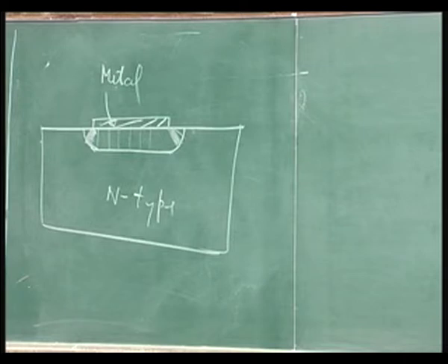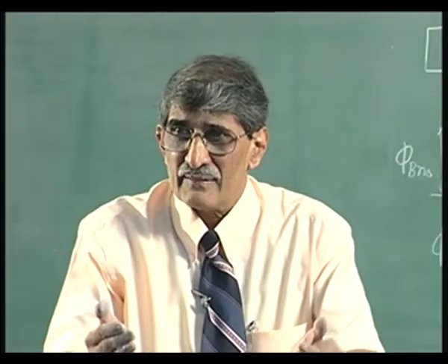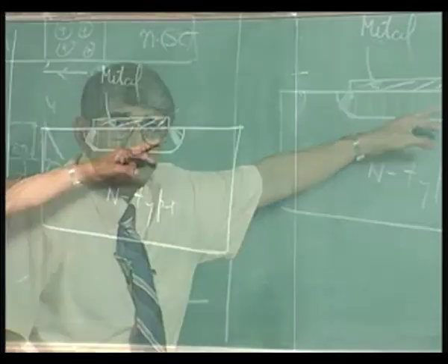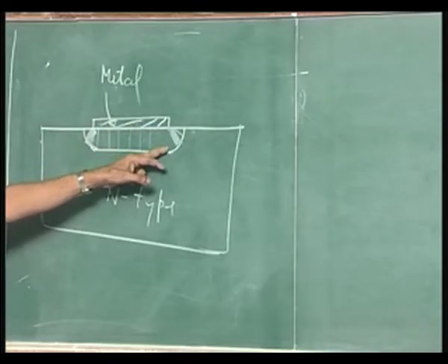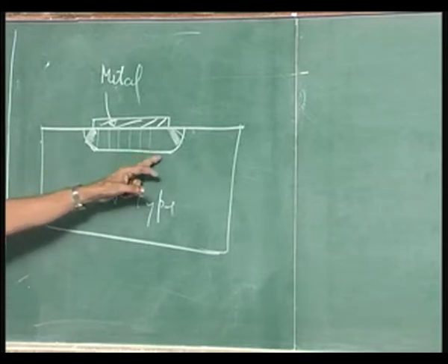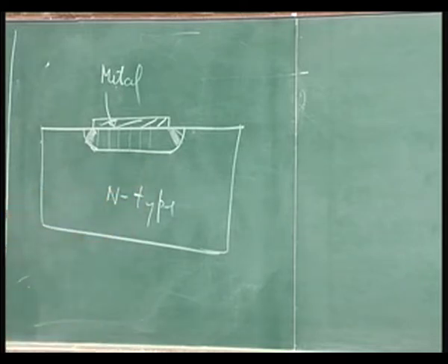Just like in the power devices we usually see, wherever junction curvature is there, you get the field crowding. Here, instead of a junction, you have an abrupt ending, as a result there will be a crowding effect here, field crowding. The moment you have field crowding, what happens? E peak is high there. When the E peak is high, both the effects come into the picture.